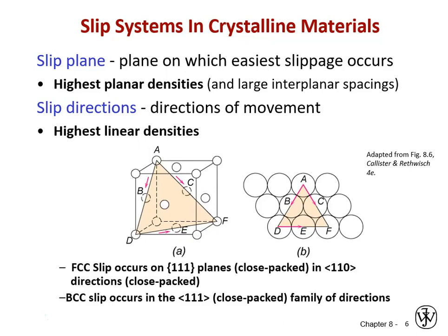So for the purpose of this class, it's obviously more complicated when we get into polycrystalline materials, but we do need to remember that for our two most common crystallographic systems for structural metals, the 111 crystallographic plane in the face-centered cubic system, the FCC system, is our close packed plane, and that is going to be the plane upon which dislocations will move easiest and move first.